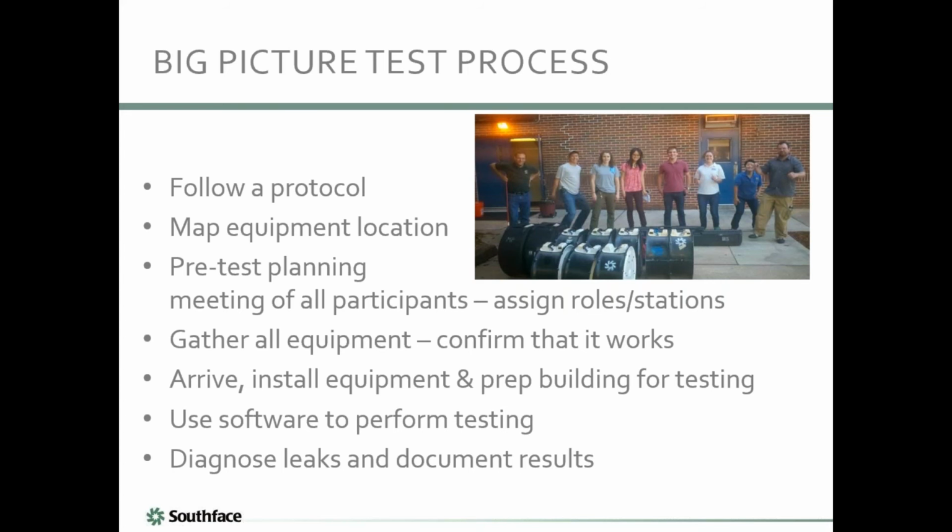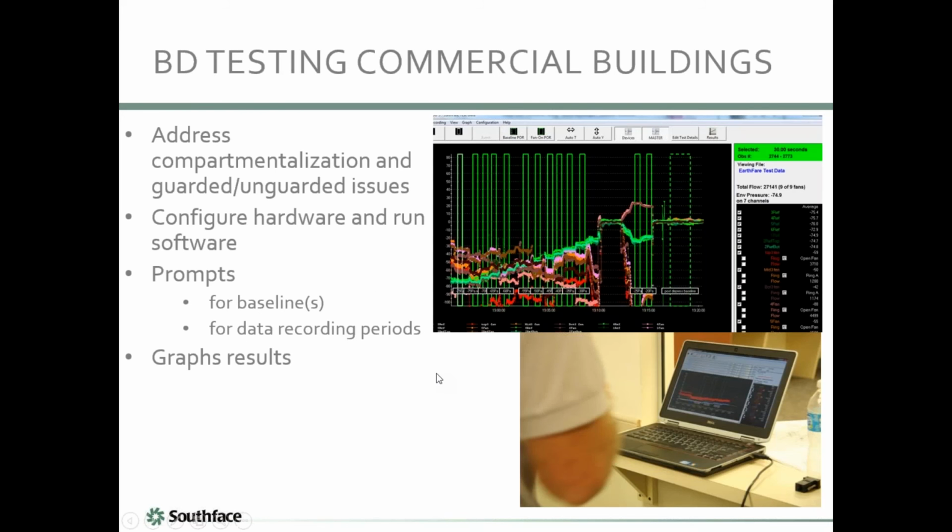So you're going to need to determine in advance, do we need to be able to tape off a kitchen range and or kitchen hood in an existing building that's been in operation? So it's going to be greasy and disgusting. How do I deal with that? Do it from the outside. I think that's the lesson learned there. Yeah, we learned that on hoods. Now, if it's a brand new kitchen, we've taped some from the inside, but generally, from the outside is easier. So there's going to be different types of buildings, and they're going to have different issues that need to be identified beforehand and determine how you're going to address them when you're actually setting up the test.